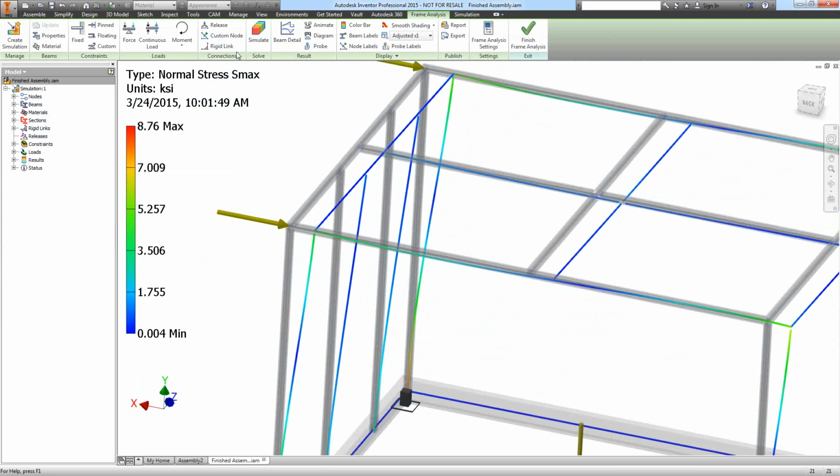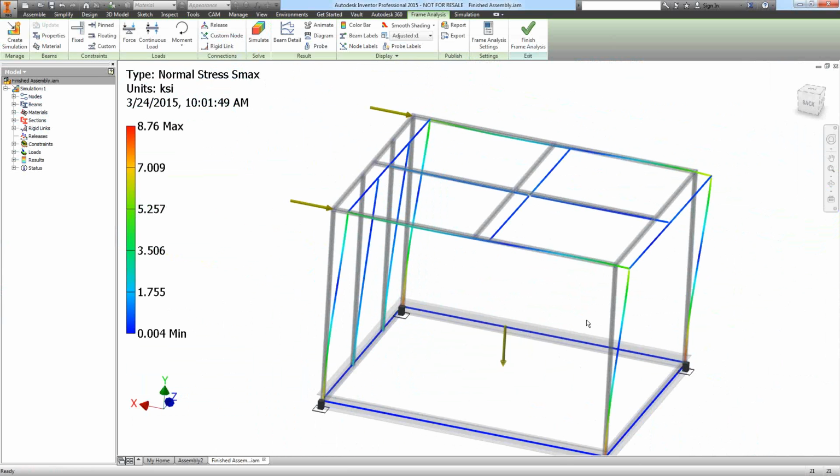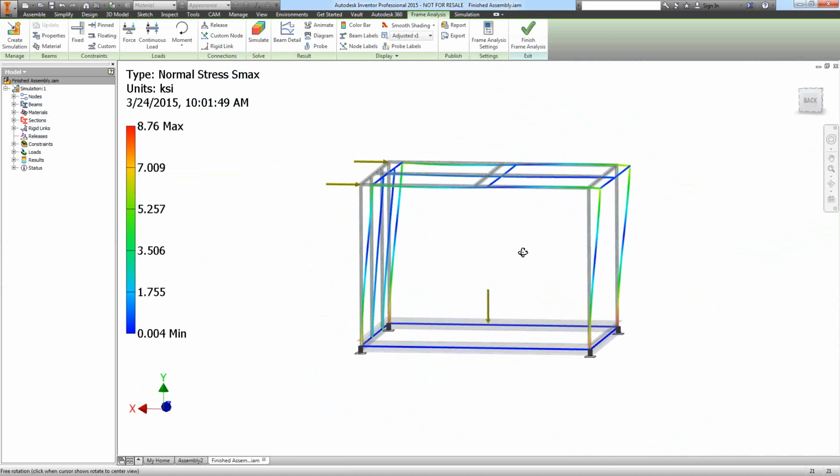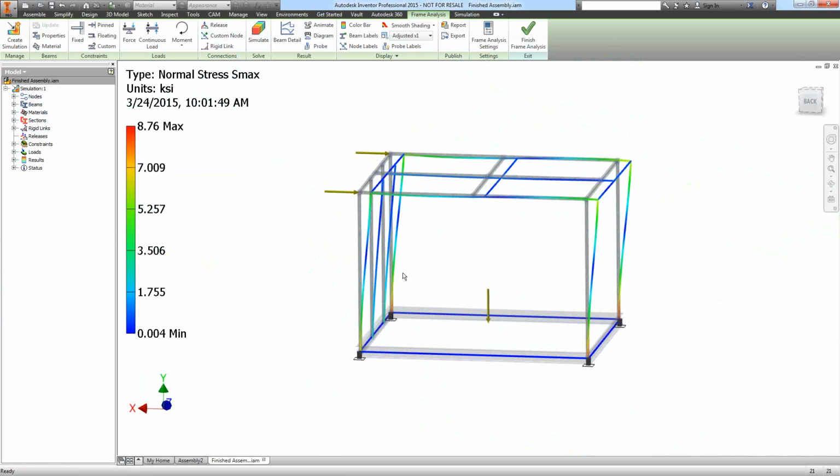So ultimately, if it's just adding stiffness, like in this case, we can see in this part it's not very stiff, right? It moves quite a bit because of these big open areas. If I was going to weld a plate on this corner, ultimately I'd be saying it's almost like taking a point here and rigidly affixing it to a point over here.